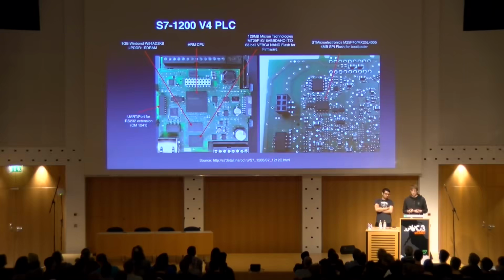Here we wanted to have a detailed view on what the actual processing unit inside this board actually looks like, and what you can do if you really want to find out. You can do some decapping, and this is what we see here. The result of this, we can see that at the core of it, it's a Renesas ARM Cortex R4 from 2010. And if you afterwards are more juggling with the software side of things, you may also want to find out the actual revision number, what it supports inside the ARM standard.